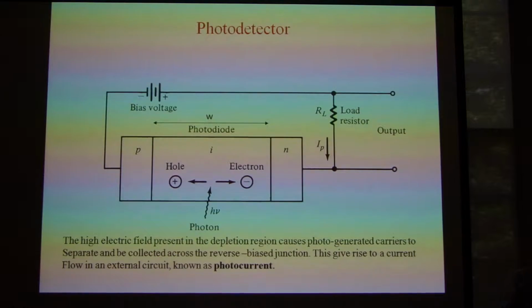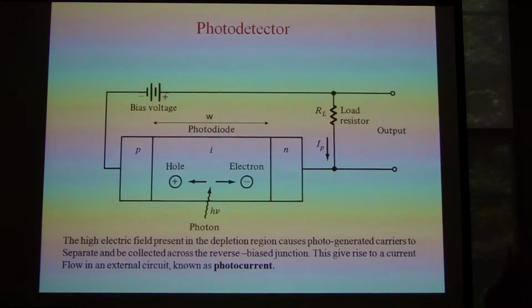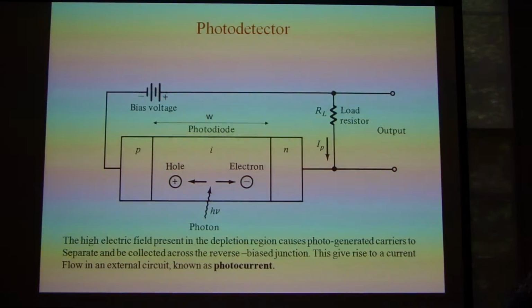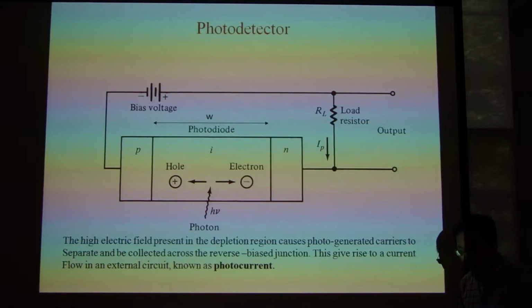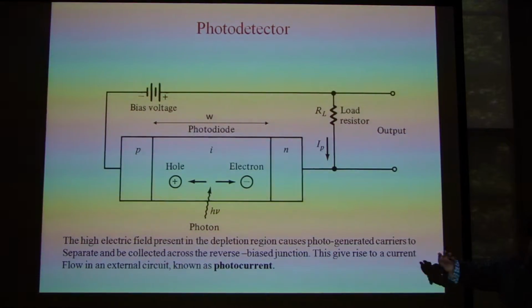Then we also have, if you think about it, LED is something that can emit light, and a photodetector is something that can collect light. One is LED converting electrons and holes into photons, but the photodetector converts photons into electrons and holes. Then you generate this current. If you detect the current, then you can detect how much light intensity you have, right? So if you compare LED technology and photodetector technology, they're really, really similar. One is forward biasing, and the other is reverse biasing. Can you tell me which one is forward biasing and which one is reverse biasing? Think about it.